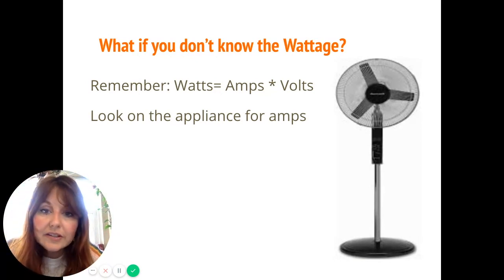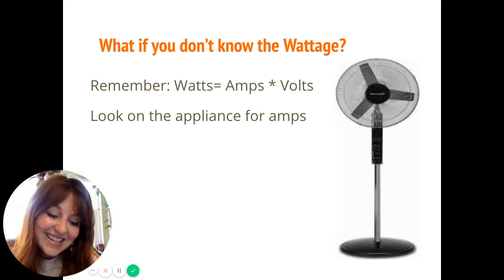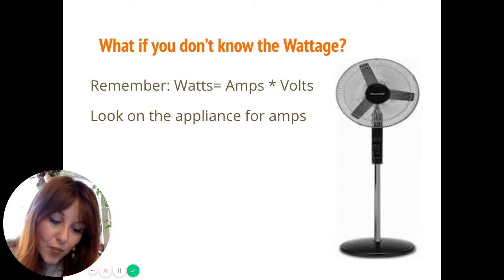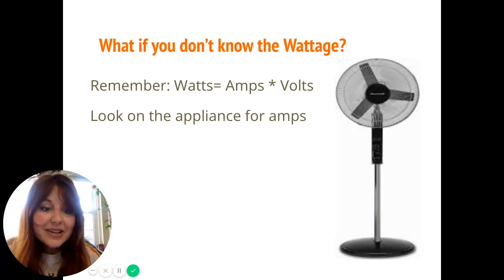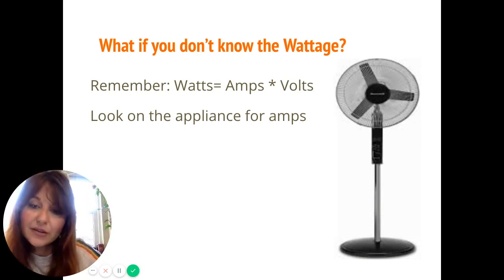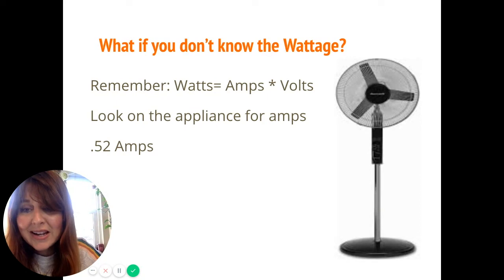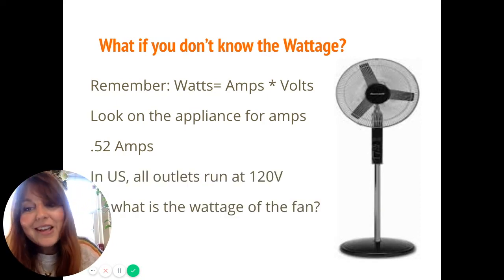No, you're totally useless. Okay, so I can look on the bottom and see that she uses 1.8 amps. And I know she's plugged into the wall, which is 120 volts. So really quickly, 1.8 times 120 is 216 watts for Alexa. The example I think uses this fan, which is 0.52 amps, 120 volts. What is the wattage of the fan? Same idea as what I just did with Alexa.